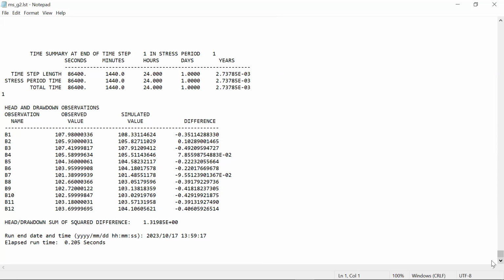Given this range, it will update the values, create the model, run the model, get the simulated value, compare it with the observed value, and get the SSR. For iteration 1 it is one number, then for iteration 2 this number might be 1.1. It will keep improving until it reaches the stopping criteria. The stopping criteria could be, say, 20 iterations, and let's say the final value would be 0.01.